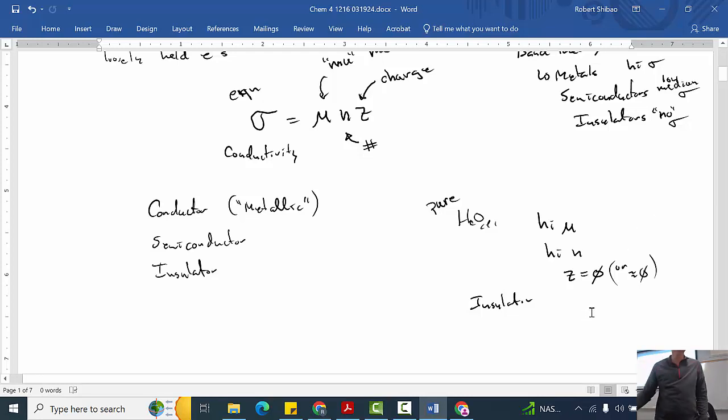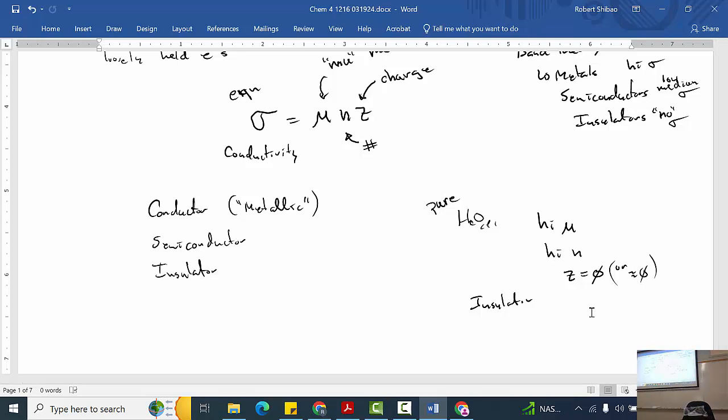This is how we can tell the purity of our water. The way we check our water purity is we stick a multimeter in the water. Actually, there's a multimeter set up here. And we measure the resistance of the water. The resistance of the water should be mega ohm. If we have mega ohm resistant water, then we know it's pure. If the resistance of the water goes down, then we know we need to change our ion exchange resin, which is like the sponge.